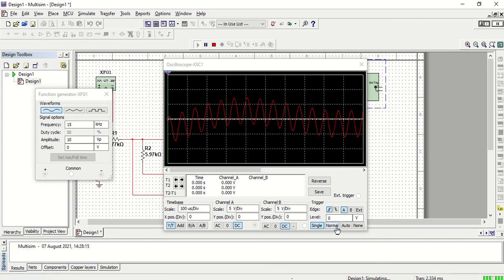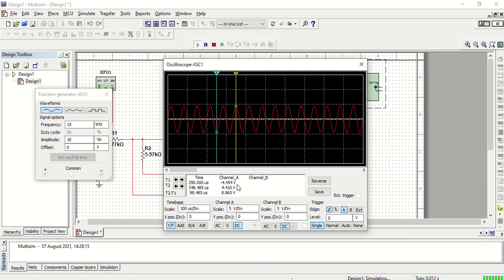Now if you measure the voltage, it is 8.86 volts. So like this you can see the voltage has decreased. So like this you need to take the output voltage values for different frequencies and plot the graph. The graph will be almost similar to the amplifier graph. How you get it in the amplifier, like that only this graph will be similar.